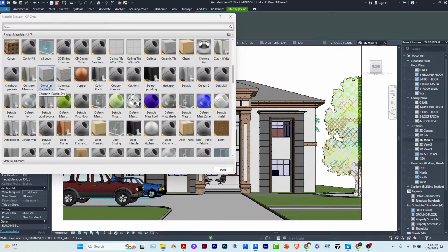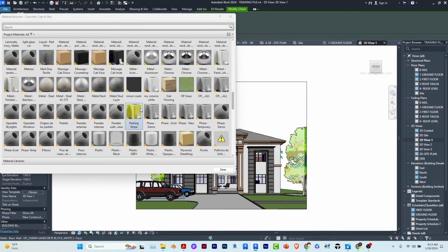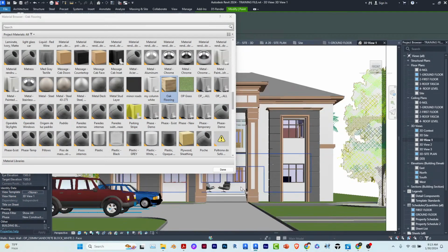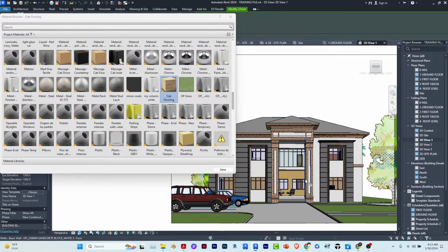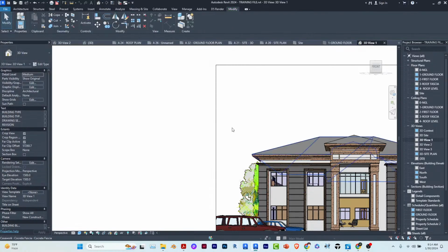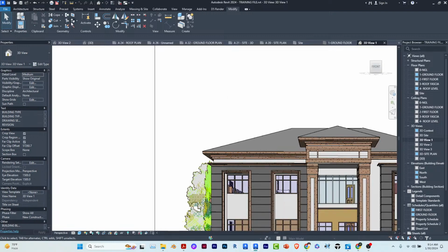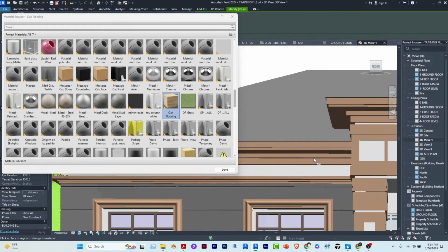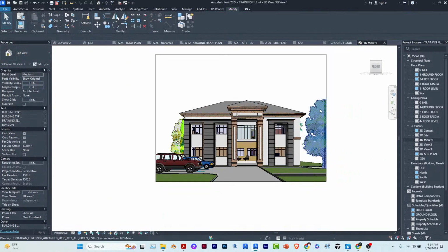So this is concrete, masonry, cast in situ. I don't know all the materials I'm applying, but I'm just giving an example. The same thing with any wall at all. If I wanted to change maybe this particular wall, give it a wooden filling, just click here and apply it. Although the wall runs through, so everywhere here is wood, but you get the picture. And you may not be able to apply to a model in place element. Those ones, you can't just paint them. You need to be editing them for you to paint them. So these are two basic ways to go about materials.